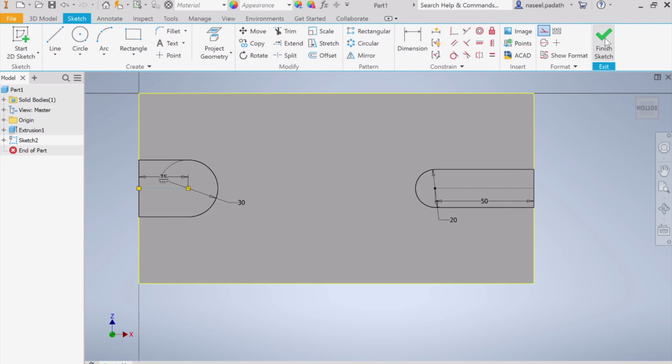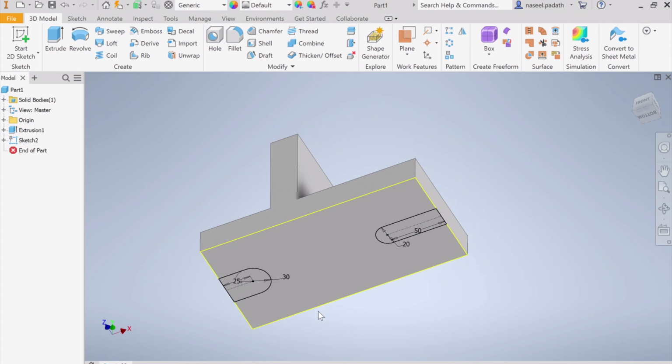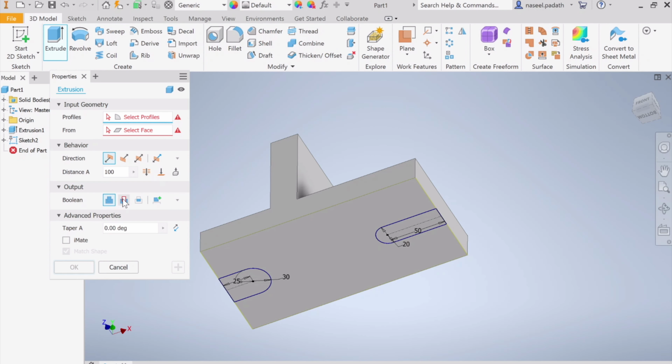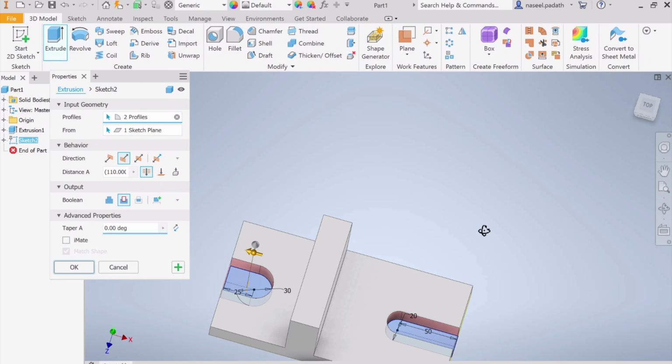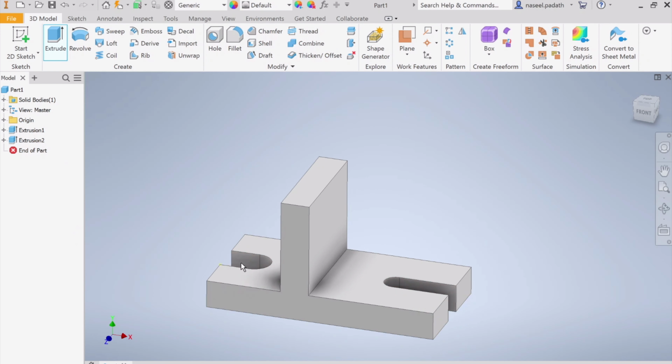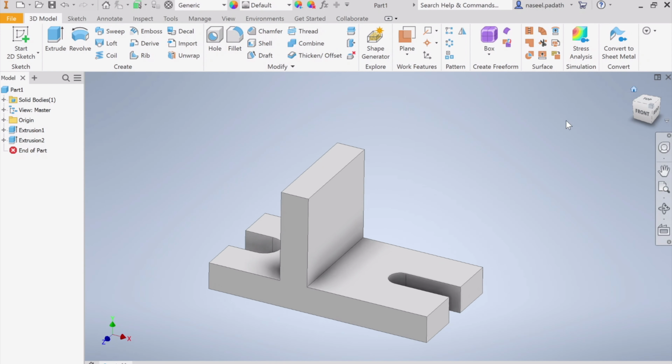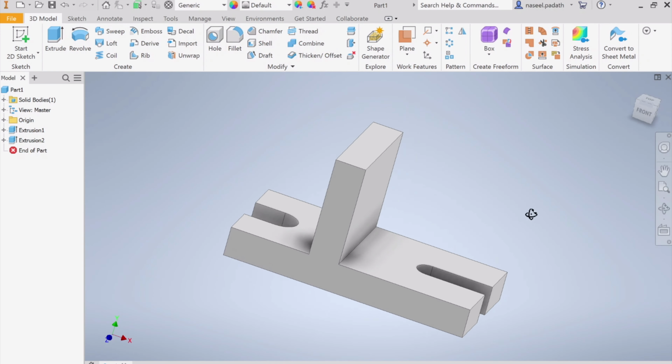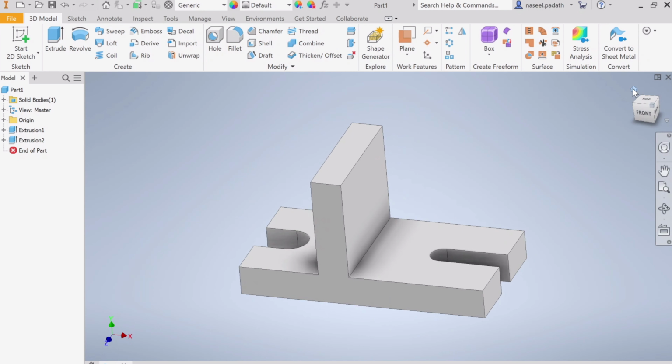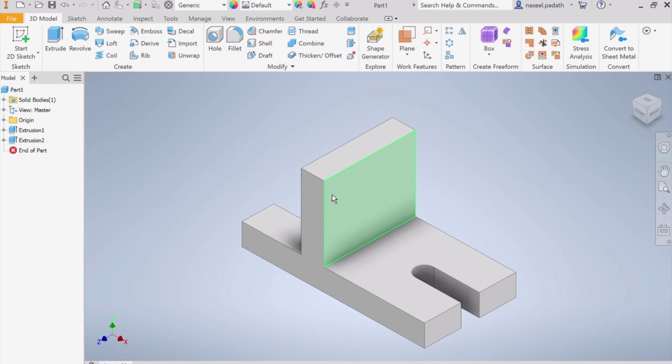to cut. So finish the sketch, and then choose extrude. I'm going to make a cut and make sure it is a through hole. You can pick the first surface and the second area. Now you can inspect. We managed to cut the hole, and click OK. And return back home. Now we managed to make those two cuts, and finally we have to make this shape